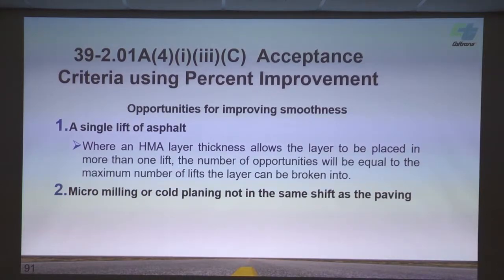Okay, micromilling or cold planing not in the same shift as paving. We talked about that earlier. That's basically how that spec reads. So if you have the standard special provision that allows the surface to be open for up to 7 days, then that's an opportunity. But if you don't have that special provision, and the specs default to forcing you to pave over that cold plane surface the same shift, it's not an opportunity.